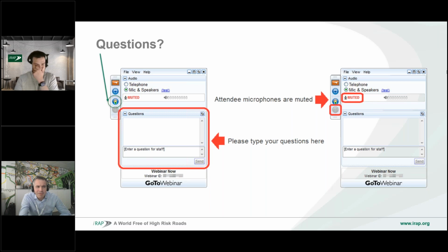So for example, the calibration factors will take care of things like what's the vehicle fleet like, what's the drink driving behavior, seatbelt wearing, how many people in the vehicles. Those are all the kind of types of things that are actually compensated for in the calibration factor. It'll just keep those consistent because they're not changing from one to the other. So when you process your data, it'll actually come out with brand new fatality estimations saying, based on those changes, this is what your new fatalities would be.